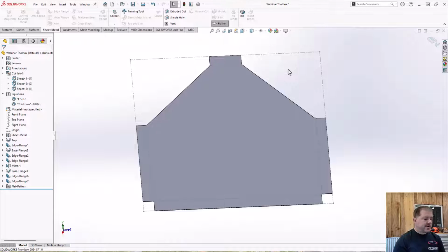And so that's typically what we use, and a K factor of 0.5 is relevant when you have things like paper. If you're going to bend a piece of paper and it's going to have a bend radius, it's not going to be a crease. When you unfold that piece of paper, it's not going to be longer because you sort of rolled it a little bit. That's a K factor of 0.5. No stretch, no compression. It's just going to bend and give you equal compression and tension. And that's true for really thin parts. It's true where the bend radius is at least 2, maybe 3 times the thickness of the material.